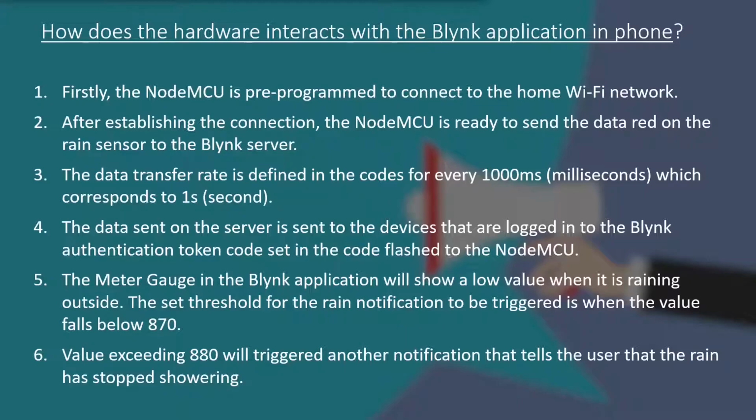So this gap of 10 between 870 and 880 provides a bit of stabilization on the system, so that it does not trigger back and forth between the two, and to have a smooth transition between the two. It will not be stuck or stutter in moving in or out, whereas when there is no gap at all, the difference of 10 is quite significant.